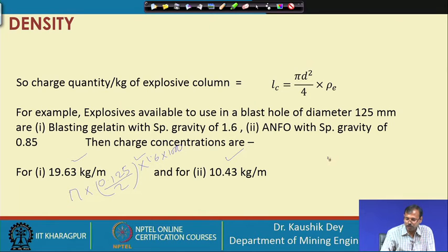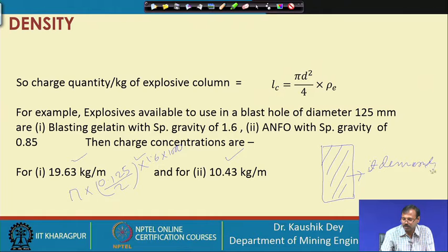So, in case of a very strong rock mass, if the rock mass strength is high and it demands more charge concentration, increased charge concentration, in that case we should go for blasting gelatin, not for the ANFO. But for the weak rock mass we should go for ANFO instead of choosing the blasting gelatin.